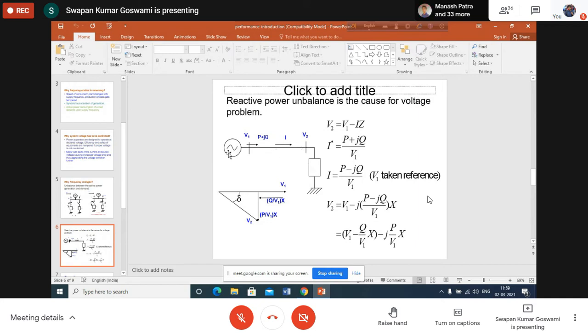We are assuming that our system is a high voltage system, because whenever we talk about frequency control or voltage control, we are discussing the high voltage part of the power system, the transmission system. I discussed in my previous class that resistance is very small compared to reactance. The X to R ratio, if you remember, X is much higher than R. For a 400 kilovolt high voltage system, the X to R ratio will be of the order of 8 or 10. If you go to higher voltage, the ratio will increase. If you go to lower voltage, this ratio will decrease. If you come to the distribution level voltage, resistance and inductive reactance will be of similar magnitude.